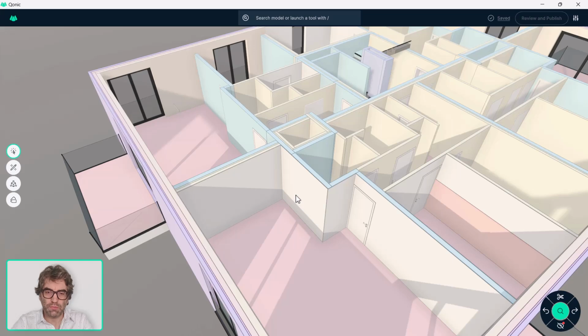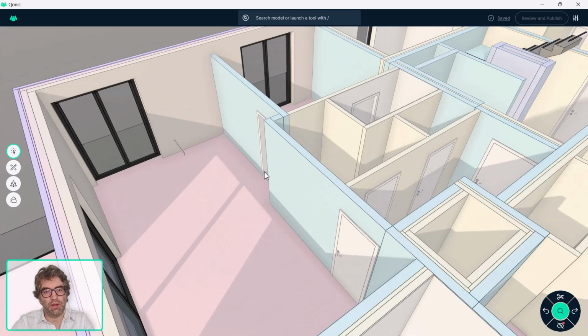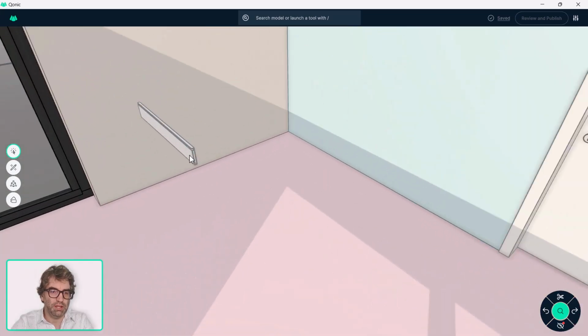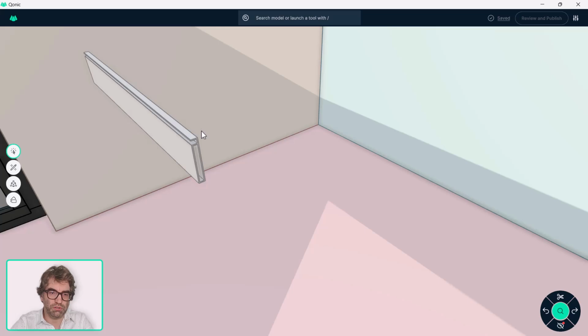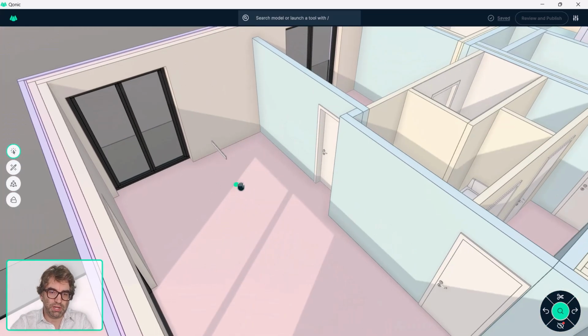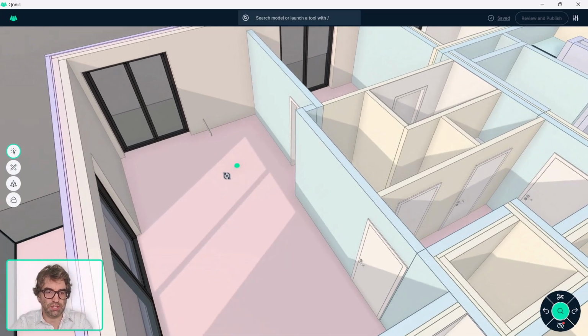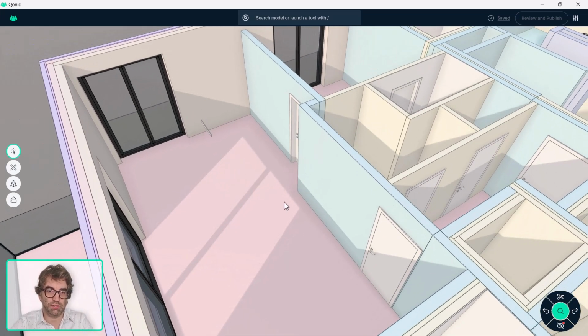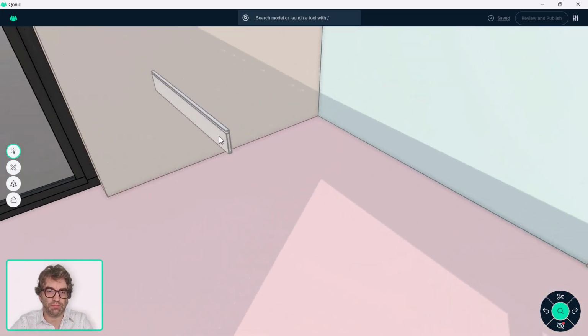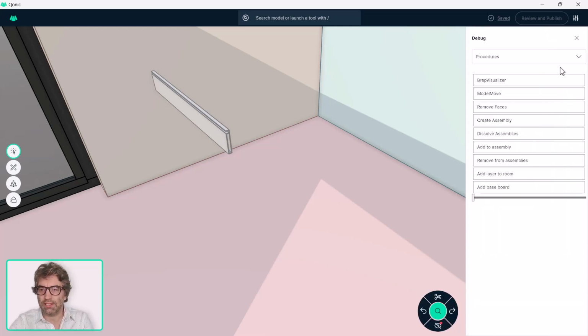Along the same lines, we're thinking about certain types of detailing which are typically cumbersome, like a form of sweep details. For instance, if we want to add a baseboard like this around this room, we would typically have to go into wall settings to define these baseboards for different wall types that are around the room, or we would have to manually follow some sweeping path to create the sweep. So we're thinking about how to make that easier, because if it's too cumbersome, it doesn't happen. You don't have the correct quantities in your quantity takeoff.